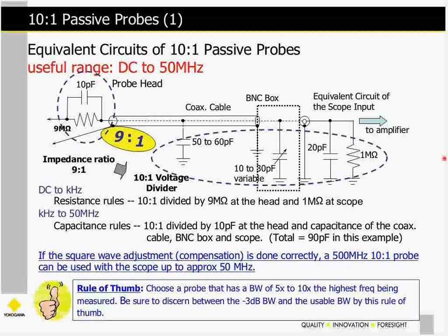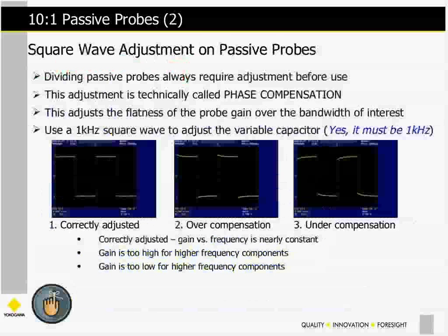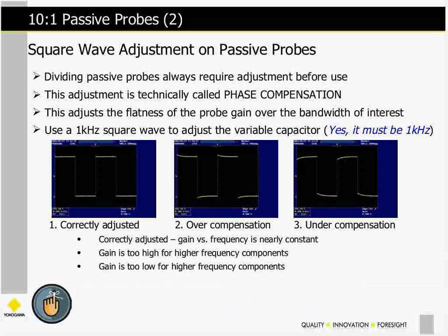And again, you can stick with the 10 to 1 rule. If you have to, you can cheat a little, and you can do a 5 to 1 ratio. You could use this probe a little bit higher. I wouldn't go past 100 megahertz with it in a pinch. At 50 megahertz, you'll want to consider an active probe, and we'll talk about that here in a few minutes.